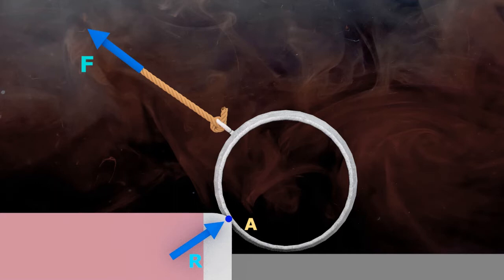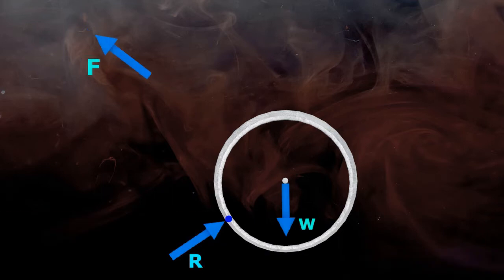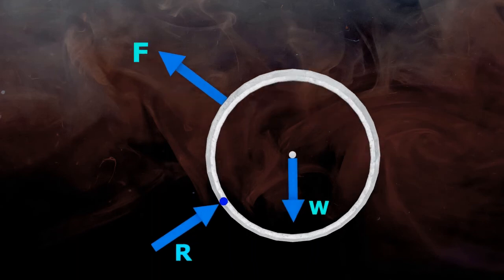Now, apart from support reactions, one more force acts on object and that is self-weight W. Self-weight of object always acts in vertically downward direction through the center of gravity. So these three forces act on cylinder. Remove the support and replace them by forces or reactions and this is the free body diagram.